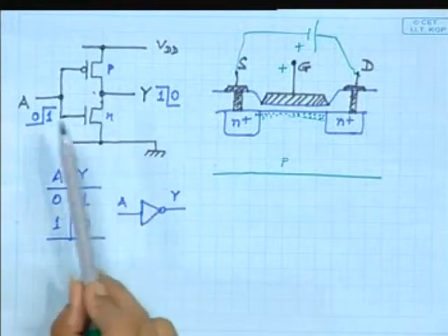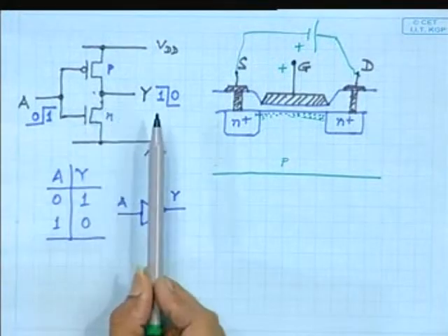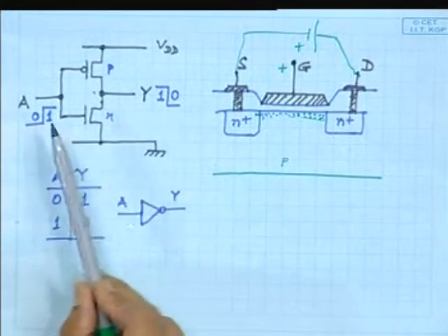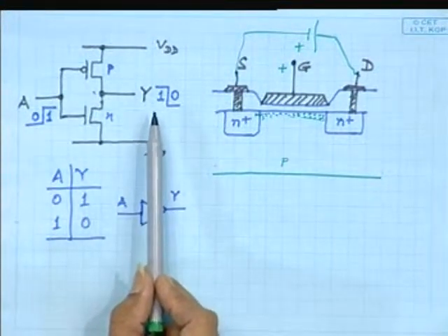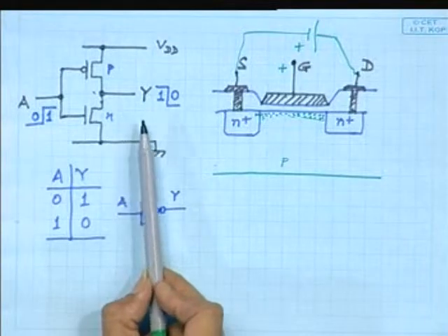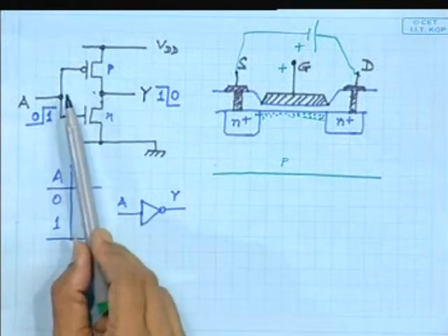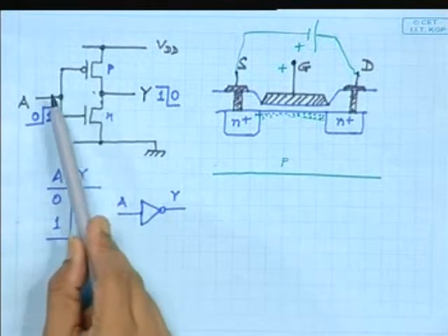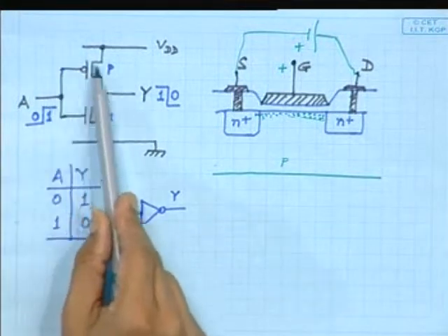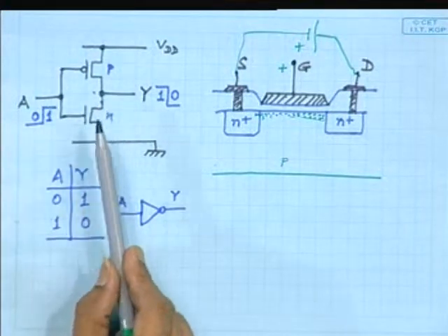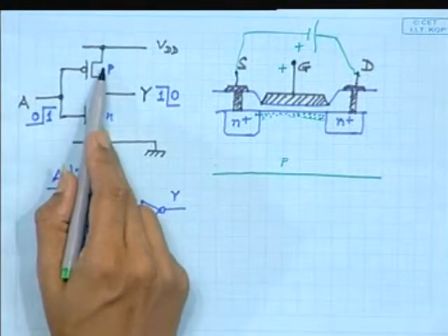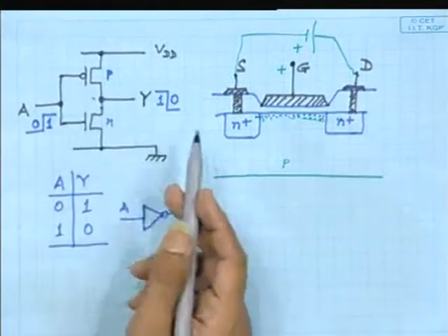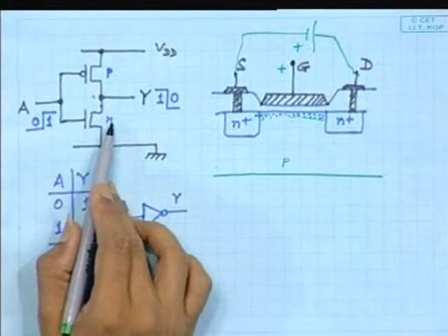Okay, so digital, sometimes we treat it as just something which deals with logic 0 and logic 1. It is not really that, particularly when we are talking about digital VLSI. Then we need to calculate power consumption. So if we just think about the power consumed by this inverter, how do we proceed? We have to find out the mechanism by which one transistor is going from an on state to off state or off state to on state.